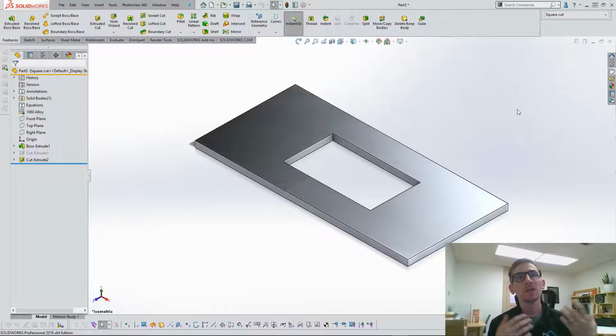Okay, so these are some of the considerations of when do I do configurations and when do I not. With my experience, I've recommended to companies and SOLIDWORKS users, hey, do configurations for preliminary designs. Those are designs that you are trying to come up with that are not going to be released yet. That way you can present them and not make a whole bunch of part files.